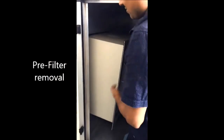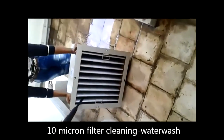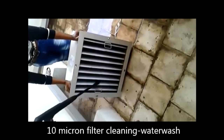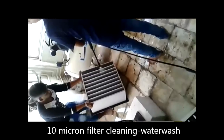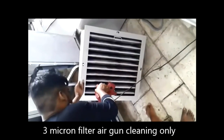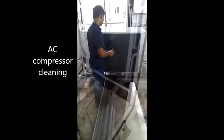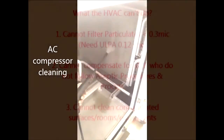These are the 10 micron filters. This is the casing which is removed once a month. The 10 micron filter can be water washed, as shown here, to remove all the dust. This should ideally be done once a month. The 3 micron filter should not be water washed. It should only be air washed to remove all the dust. The AC compressor is then cleaned here.